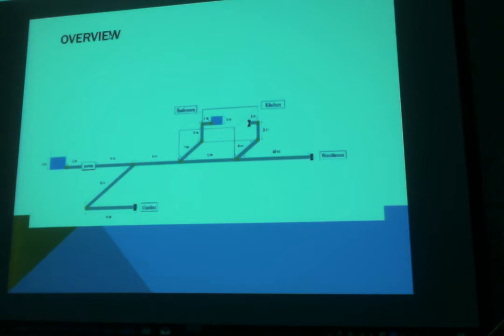Now, for our project, we're told a pump delivers a steady flow of water from a large tank to a house. During the pipeline, the flow is split to 4 different destinations: the garden, bathroom, kitchen, and a warehouse. The total length of the pipe network is 60 meters. We are asked to find and use appropriate pipe fittings and a pump to build this water distribution system with minimum cost and pump head.